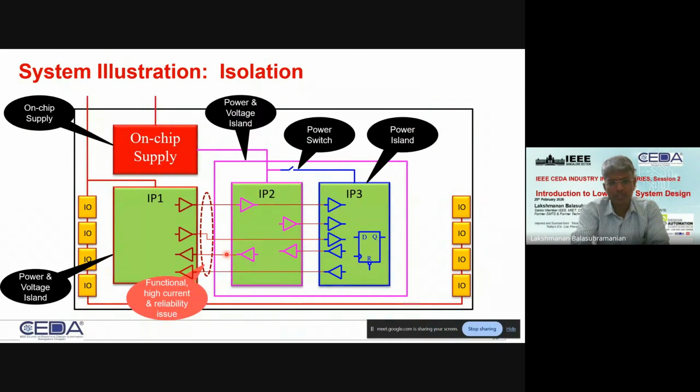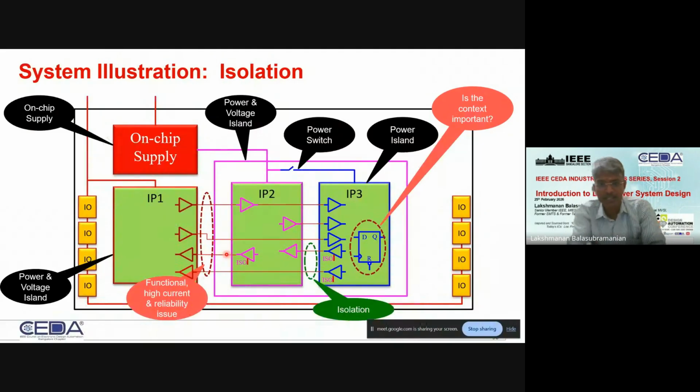With that, what is the solution for that? Again, without getting into the circuit level details, at system level, there is a concept called isolation. Conceptually, what it does is I can have cells only at the interface. It may have billions of nodes inside the IP3, but I may have just 100 or 1,000 nodes that are talking to the external world, outside the IP3, to other IPs which may be on.